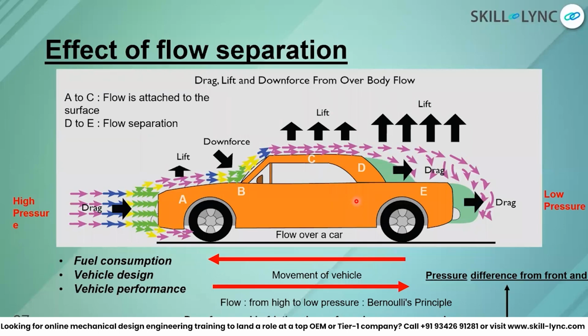So that's one place where you can see the application of flow separation is very much important when you're considering the fuel consumption of a car. The same kind of principle can be applied to F1 cars, trucks, buses, any automobile you take. In fact, aircraft also. But for aircraft, the physics is a little bit different. There you want more lift and less drag. So that's one difference.